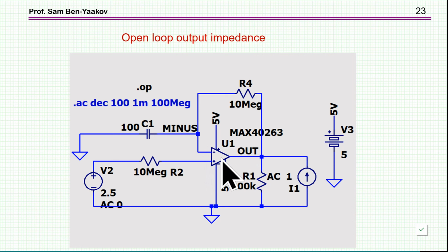Now, you cannot run simulation open loop, similarly that you cannot run measurements in open loop, because the gain is very high of operational amplifier. There is noise, and whatever you do, you have to trim it very carefully. So the best thing to do is to close the loop, and here it is closed. It's in a follower here, okay? There is a resistor here, that's it, it's a follower. But I've put here a very, very large capacitor so that it's 100 farad. In simulation I can do that.